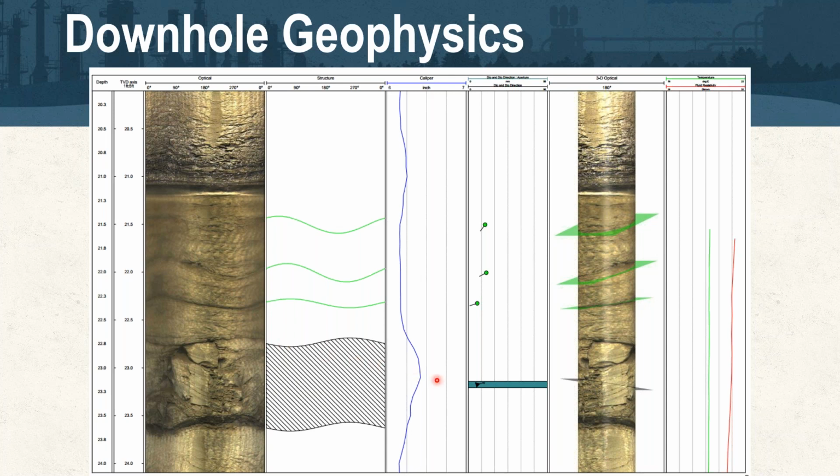But what we also want to note is that the geophysical contractor did identify some low angle bedding features directly above that could be contributors as well. And so again, coming into this idea of coming in with characterization and ultimately the remediation plan, we want to make sure that we're looking at every interval present. And with that discrete interval sampling tool, we can actually isolate these individual bedding planes and that higher K zone and actually look at the chemistry and the fluid properties of that specific area within the formation itself. Next slide, please.